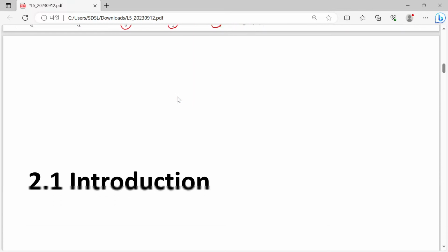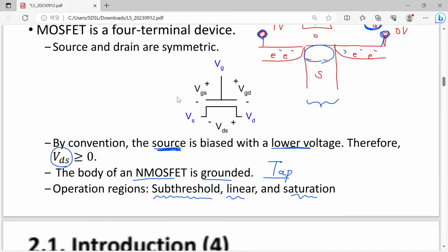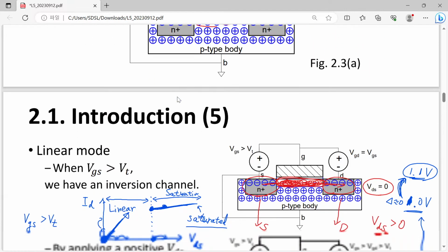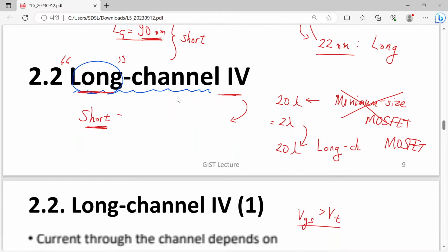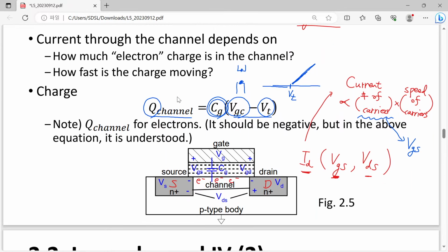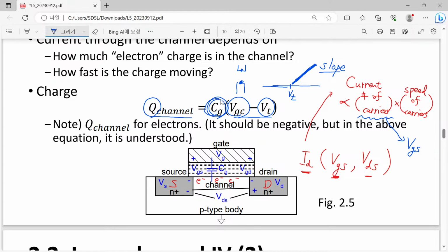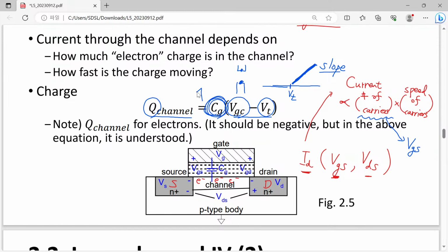So beyond a certain voltage, we will have the inversion charges. And of course, we have a certain slope because this is linear behavior, and this linear behavior is given by the gate oxide. If we have higher gate capacitance, then we will have quite steep behavior.